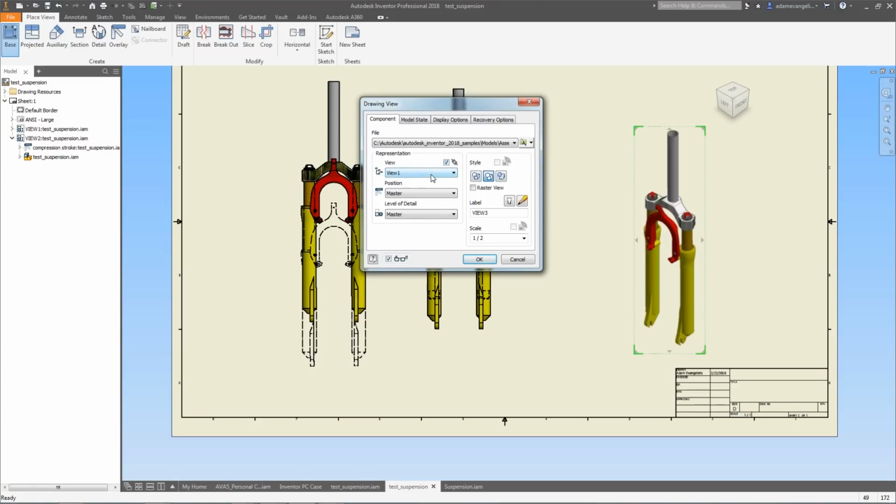And so this is a question that when I was on the Lifeline team, and I'm sure Adam, who is currently on the Lifeline team, gets weekly. Maybe it's like, I updated my model, but it didn't update my drawing. Why? That's a classic. That is the classic. And the answer 90% of the time, unless it's like some freak incident, is did you check the box with the associativity in it?